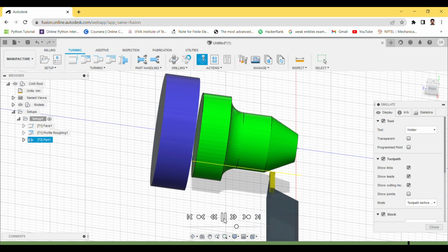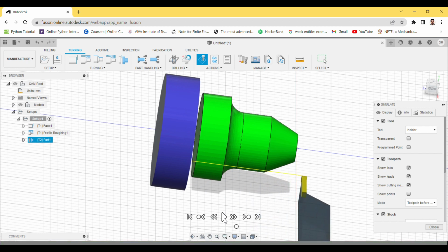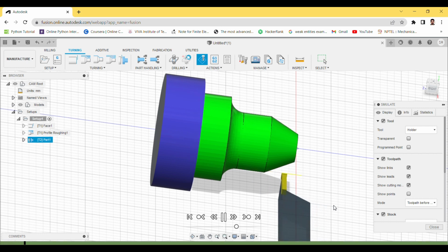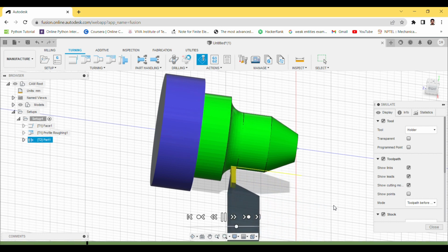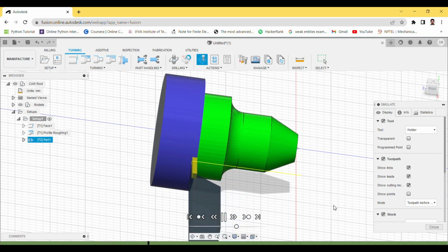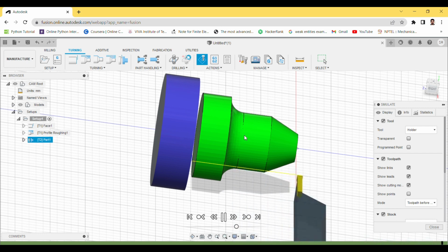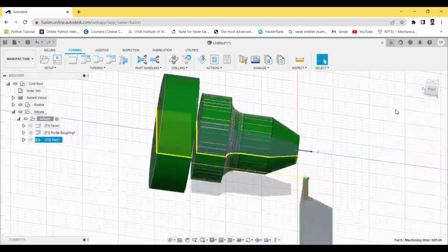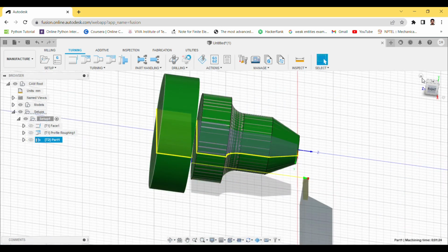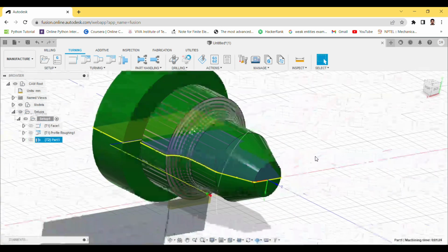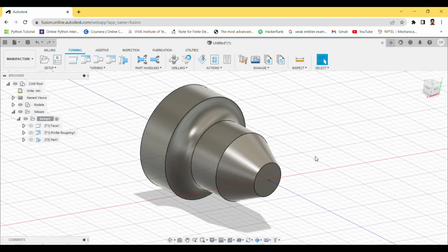So here you can see, here is your grooving tool. It is getting inserted, and you can see everything has turned green, so that means the proper grooving has happened and your job has been separated. This is your finished product and this is your extra material. Okay, click on close, click on home position, click on escape. So that comes out of everything.